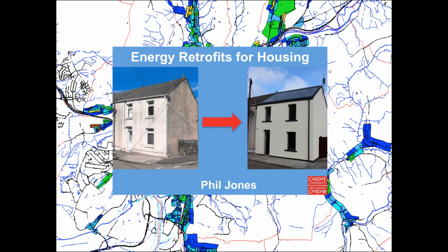I'm not aware of any foolproof systems, because people will go up into the loft and disturb them, and we've had issues of that when services are put in and the insulation is moved and it's not put back right. And of course, you also get the insulation sagging over time, so it won't retain its thickness. And that's why, even if there's insulation already in the loft, we would usually top it up to a new level.